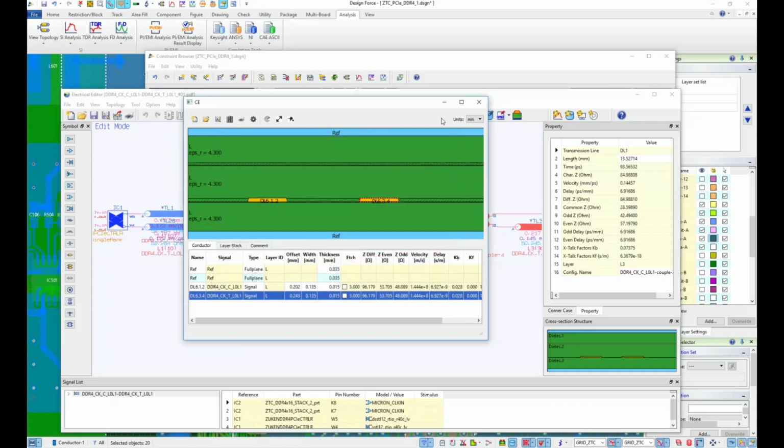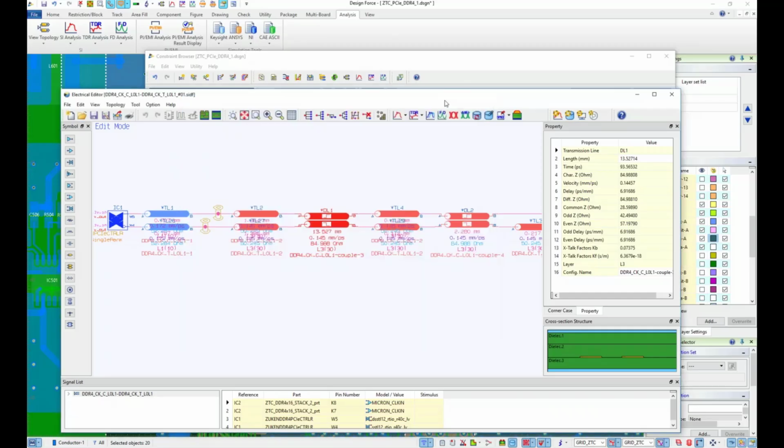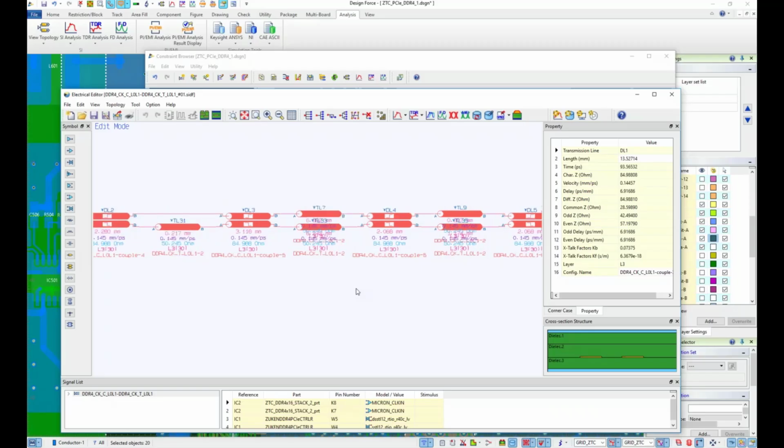So you can do all these kinds of studies, adopting the field solver results. You can pass the results, the impedance figures, into that topology, and then use the simulator to figure out what is the impact of this changed impedance behavior on the electrical performance.